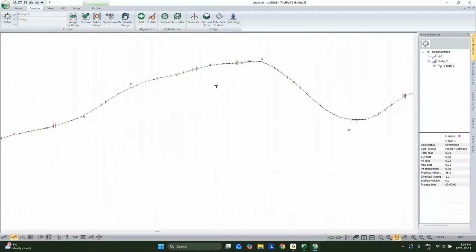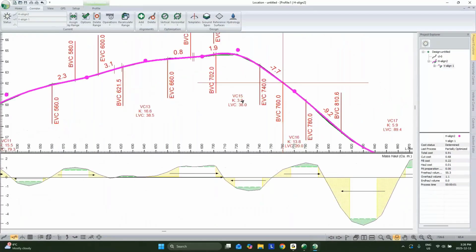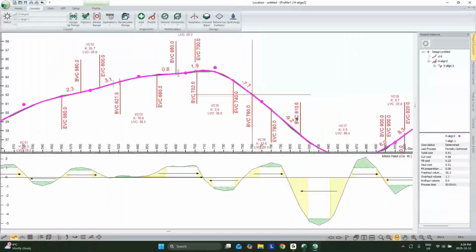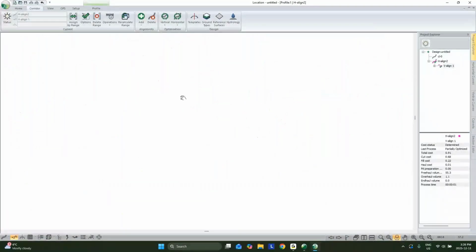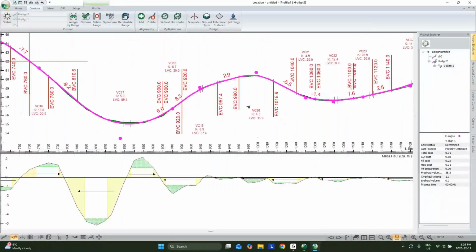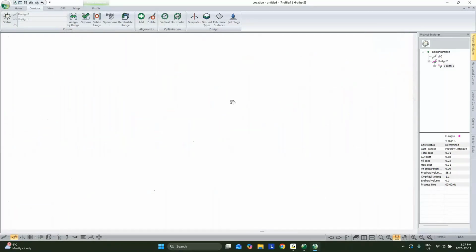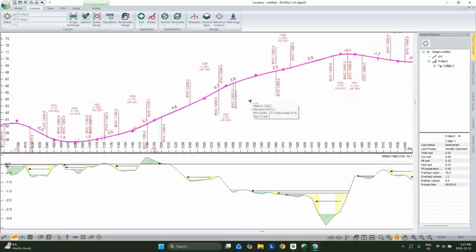And, well, then we've got this nasty vertical curve here where we've got a K of less than 4. We've got that sag close to 6, another K close to 4, K around 5. So it is a pretty tight geometry and kind of outside of the realm of what I'd like this final solution to be.